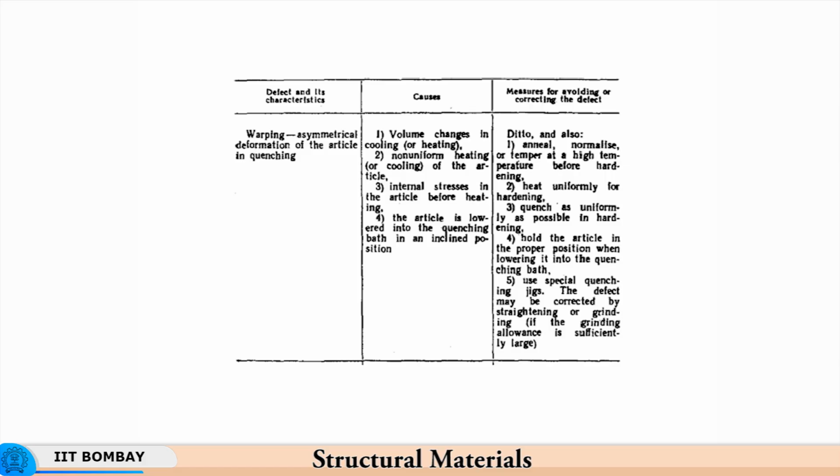So the jigs cannot be too firm, meaning they need to permit some amount of warpage, but restrict it so that only a small amount of defect remains. The basic idea is to minimize the extra material that needs to be provided. If you have very free warpage taking place, then you need much more extra material to extract out the part to the dimensions you wanted.